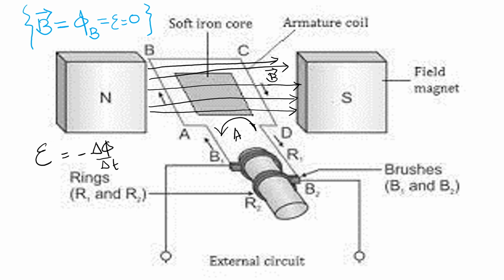So in this way, the induced electric current, as the coil is rotating anti-clockwise, during half of the rotation will generate an electric current, and that induced current will be in the downward direction.